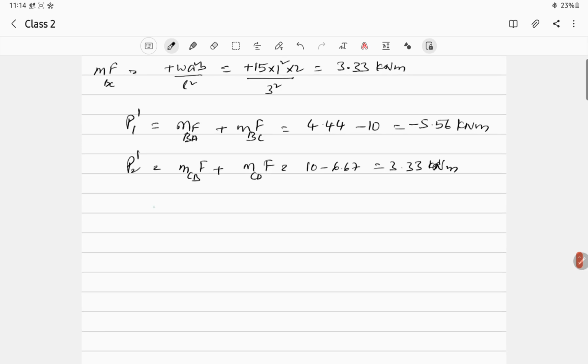The simple stiffness matrix method calculation is delta is equal to inverse of stiffness matrix into P minus P dash, isn't it? So what is this P? This P will be equal to 0. Why? Because there is no sinking of support here. So what is the stiffness matrix we have? Once you multiply this one, this is K and this is minus P dash, so plus into minus, minus here.